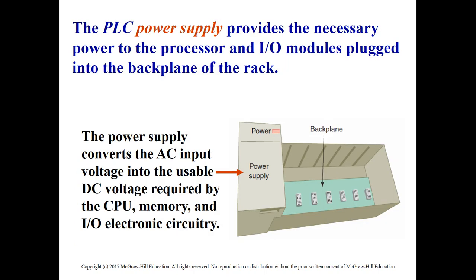The PLC is powered by the power supply unit here, or the mains. Like the CPU, the other input output modules also get their power from the main power supply through the back plane here. So you can see that when we plug in the CPU module or the input output modules, they get the power from these ports.